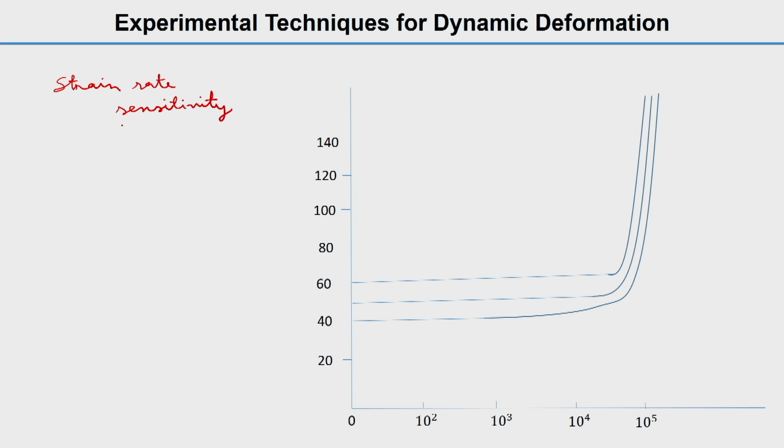So we took different strain rate ranges earlier, 10 to the power minus 3 to 10 to the power 3 per second. But we should understand these materials are very different in structure, especially the crystal structures. We have shown aluminum alloy, but basic aluminum has an FCC structure.